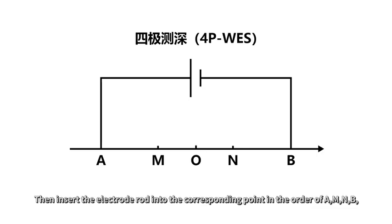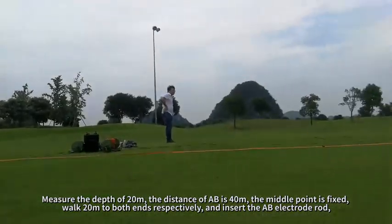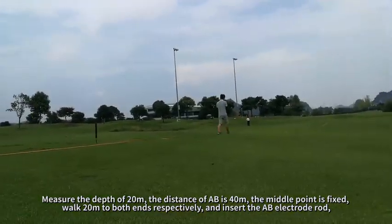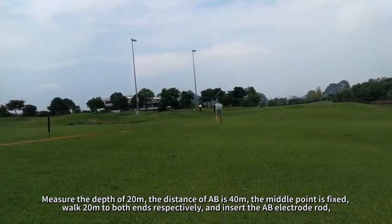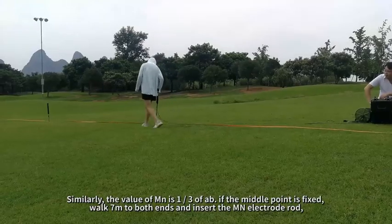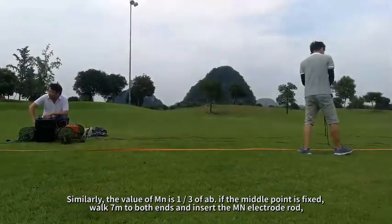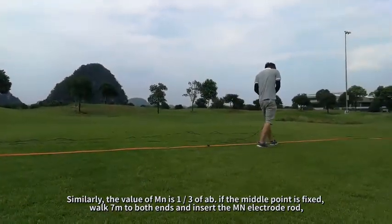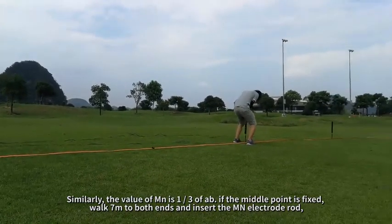Then insert the electrode rods into the corresponding points in the order of A, M and B. Measure the depth of 20 meters. The distance of AB is 40 m. The middle point is fixed. Walk 20 m to both ends respectively, and insert the AB electrode rod. Similarly, the value of MN is 1/3 of AB. The middle point is fixed. Walk 7 m to both ends and insert the MN electrode rod.